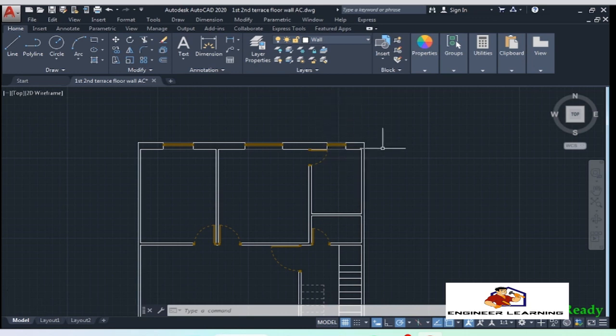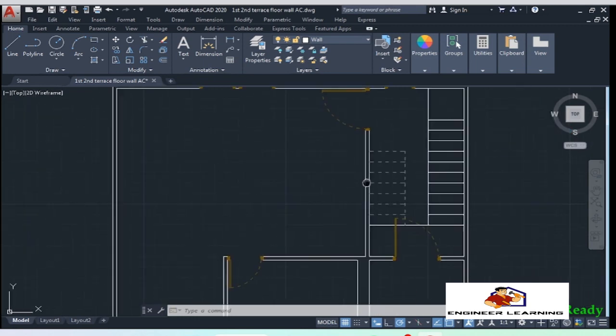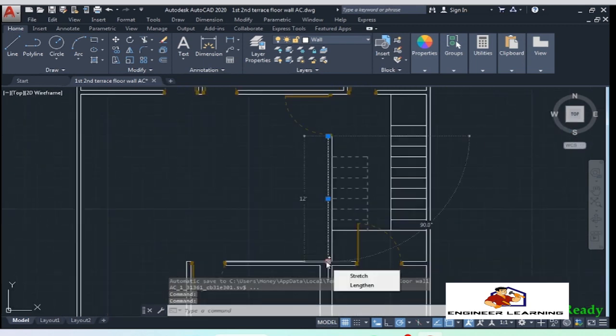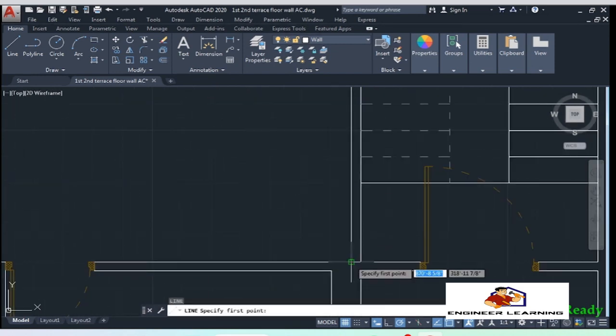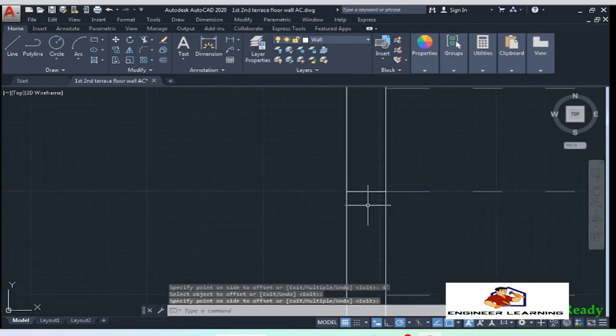The left and right side of the house is blocked by the neighbors, so we cannot place a window to these sides. Place an 8 feet wide window here for the living room. This will bring light from the staircase opening into the living room, and large windows give a feel of open wide space.